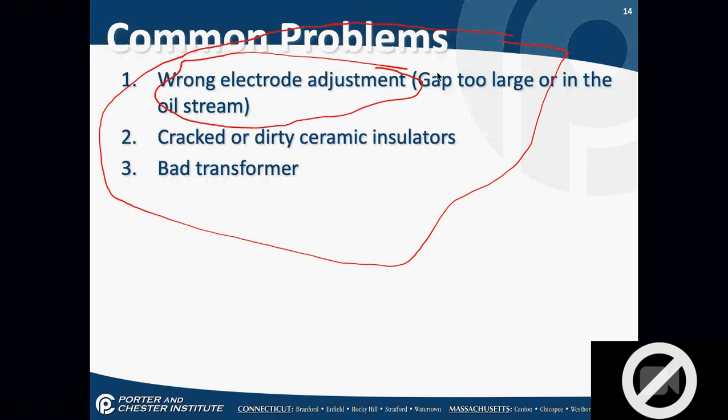The nozzle? What about the nozzle? You still have, I guess, residual oil at the tip, don't you? Or dripping oil from the nozzle? Let's hold off on the dripping oil, but if I have a lot of carbon buildup on the tip of the nozzle, it's possible that could be caused by incorrect electrodes, because it could be sparking to the nozzle instead of to the other electrodes. So that could be part of my gap setting.